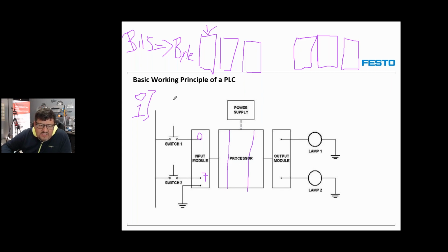Inside my PLC, there is what we refer to as a PII table, and on the processor again a PIQ table. It's called the process image input table or process image output table. Let me go to the next slide, and then I'll also explain a little more about why 0 and why not 1.